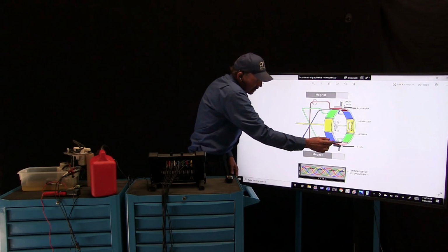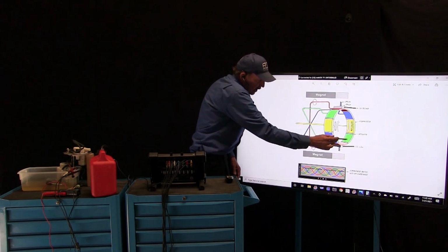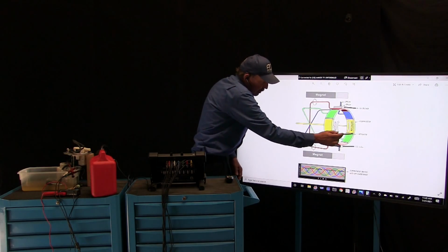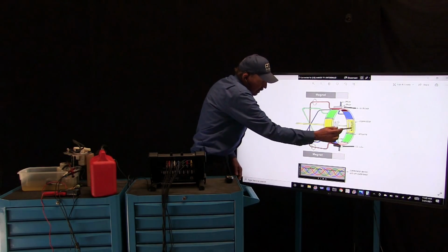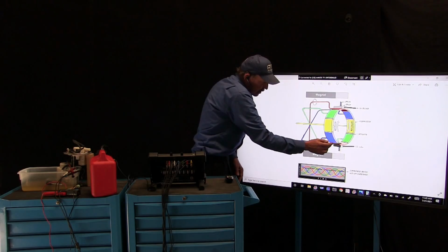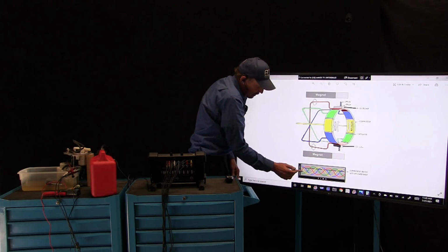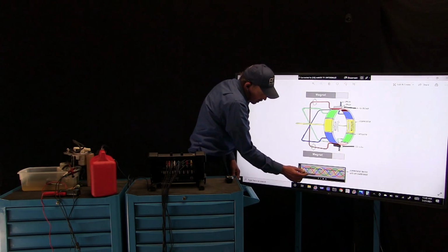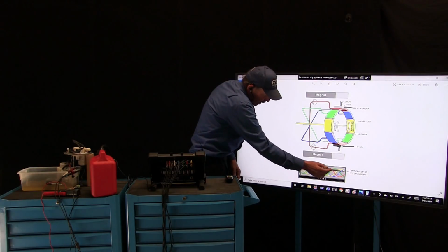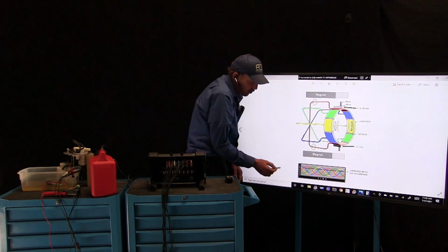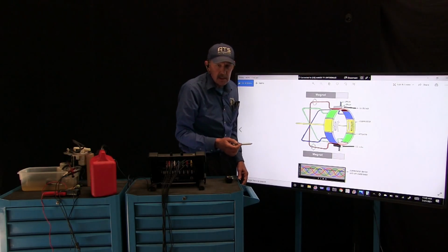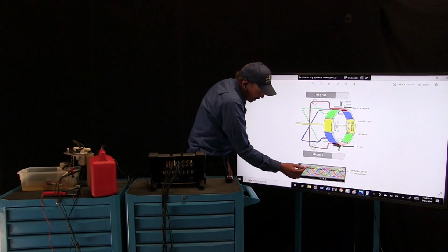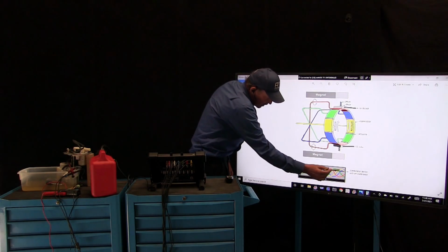As it rotates, it's going to go up onto the next commutation, and then the next commutation. In between each one of these commutators is an insulator. So we're going to roll across that insulator to the next commutation bar. Now, if we didn't have commutation bars, the signal would want to go negative and positive. This would be an AC waveform, but this is a DC style pump. The commutation bars are cutting it off at the top, so they're cutting off the tops.